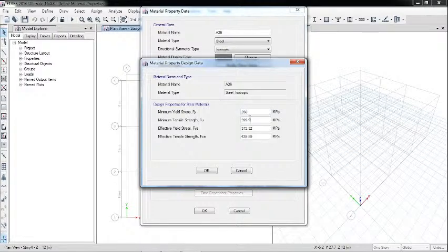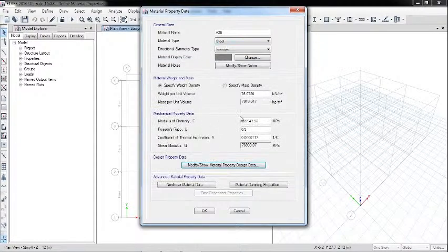So that's how you can also change these properties, but mostly we work with 250 megapascal. That value is okay. For 400 megapascal is ultimate. So you can also study here the rest of the properties, that is the Fy equal to 250 megapascal.